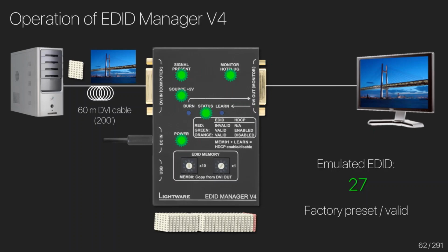An example where this is used quite well is with a Watchout media server. With Watchout, if the media server detects that the display has been disconnected, it'll resize the active area and generally screw things up, and ultimately you'll need to restart the playback once you've connected everything. So the nice way to avoid this is to have every output from the media server connected to a device that has EDID emulation.